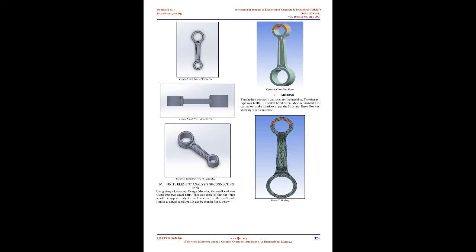A connecting rod has 3 parts: a small end, a shank section, and a big end. They can be produced as single-piece or 2-piece components. To ensure that the bearings fit properly, the piston pin end and crank pin end pinholes are machined as parallel holes. The piston and the connecting rod are coupled at the small end by the piston pin. The small end of the connecting rod will have a solid bushing of phosphor bronze or an analogous material. As the big end revolves with the crankshaft, the small end is forced to swivel on the piston pin. The bushing is necessary due to the high pressure and temperatures, in spite of only a slight movement relative to the piston pin.